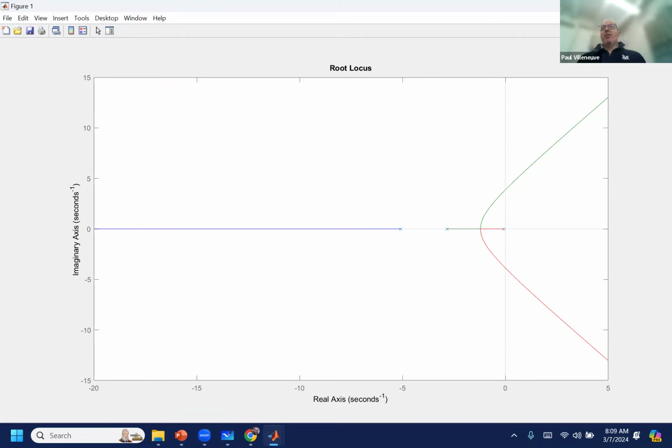But remember what we do, and I've been saying this a little bit since last semester: how many poles do you have in a system? Let's say you have 3. Then how many zeros are you going to have? 3? What if I only have S plus 1 in the numerator? Yeah, very good. If you include the fact that you have 2 zeros at S equals infinity, remember we do our limit function, you always have the same number of poles as zeros. I wasn't saying you were wrong. I was just trying to get people to think.